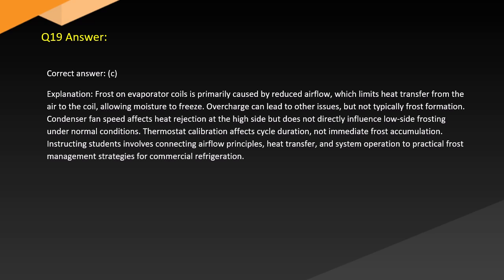Condenser fan speed affects heat rejection at the high side but does not directly influence low side frosting under normal conditions. Thermostat calibration affects cycle duration, not immediate frost accumulation. Instructing students involves connecting airflow principles, heat transfer, and system operation to practical frost management strategies for refrigeration.